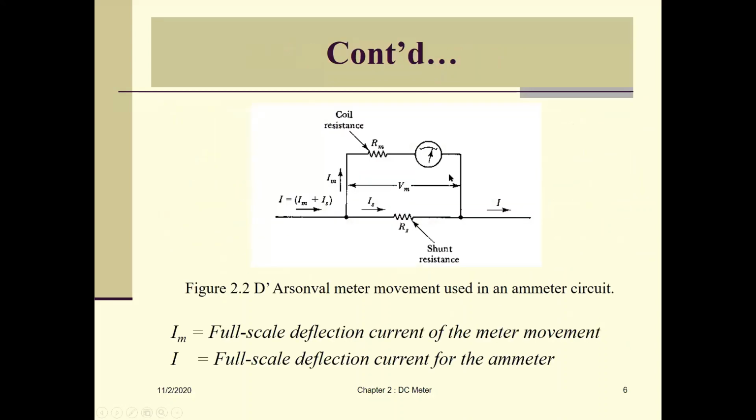So this is the concept of the ammeter. We use the basic meter movement. This one has only one range. If we have more than one range, we call it the Ayrton shunt. That is the basic way to use the DC ammeter to measure current. Maybe I recap this one for more understanding.